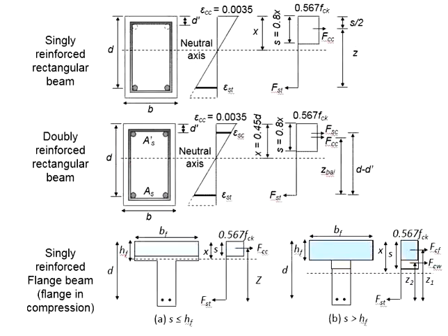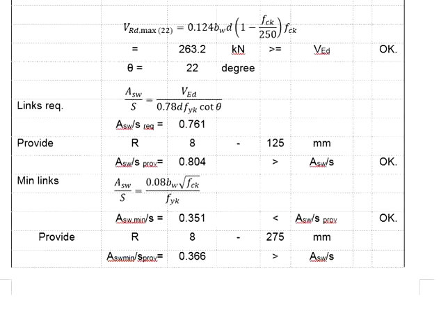Simple formula. Now you need to remember, normally shear links come in a loop. When you calculate the area of the shear link, each shear link will have two cross-sectional areas. Therefore, you need to determine the pi r square times 2 cross-sectional area and then divide by the intended shear link length. When the size of the shear link is decided, that means the area of the shear link is constant. Now you may use your calculator to test with different spacing.